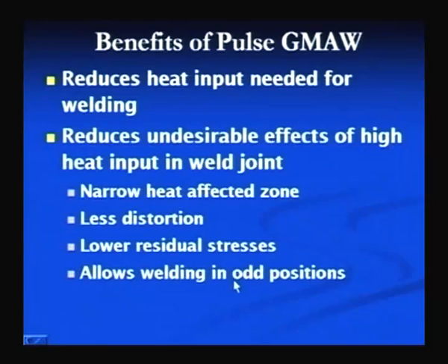It allows welding in odd positions, because heat input is reduced significantly, which in turn helps to improve control over the molten weld pool, because fluidity of the molten metal is reduced with the reduction in heat input. That helps to put the molten metal in the positions where it is required without falling down, even in odd positions.